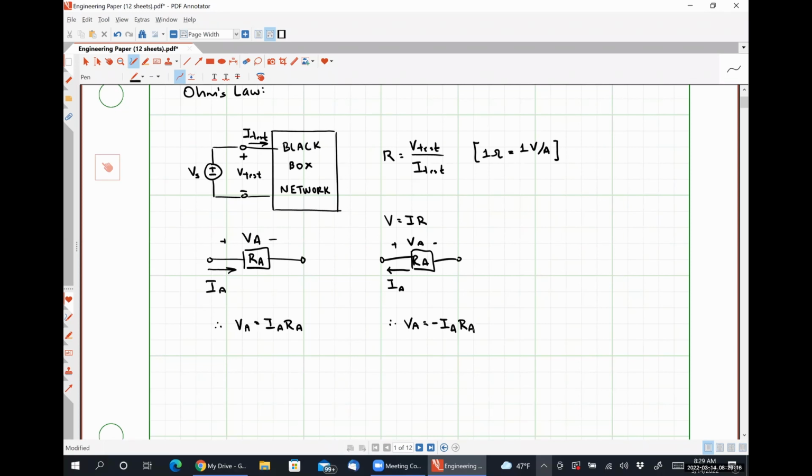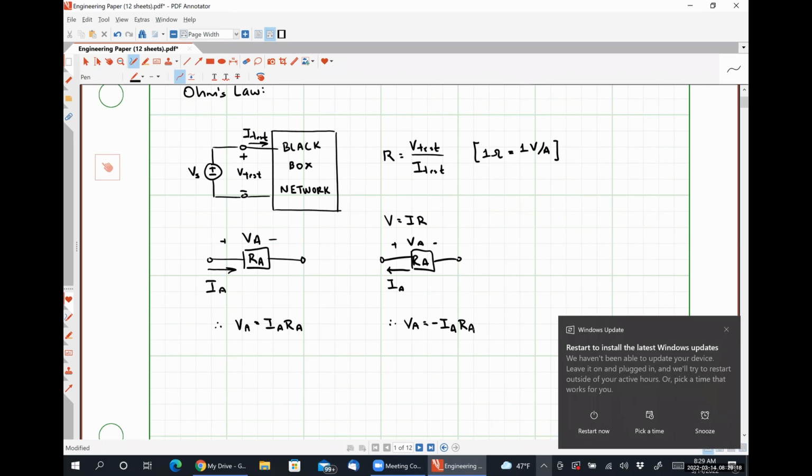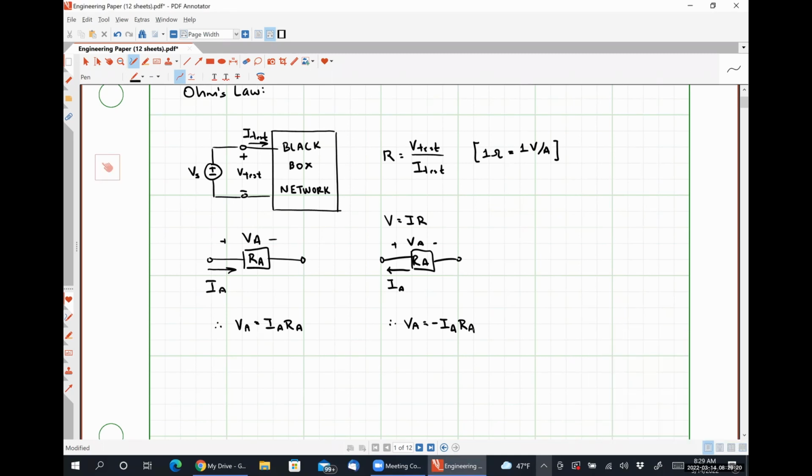And then we applied a 5-volt drop across that series combination of elements to make the LED blink. What was the purpose of the resistor in that circuit? It decreased the current going to the LED, right? So resistors are used for limiting current in circuits, okay?